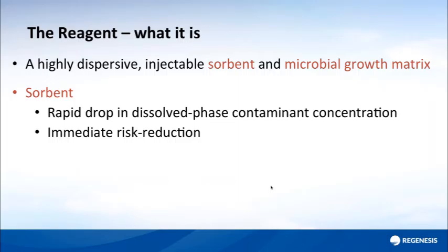And as the groundwater concentration drops, naturally the concentration in the vapor phase will drop, headspace analysis, as any analytical chemist will tell you. So the vapor intrusion risk and vapor-driven risk will also immediately drop. This can be monitored with a PID during the applications, and it is remarkably fast.